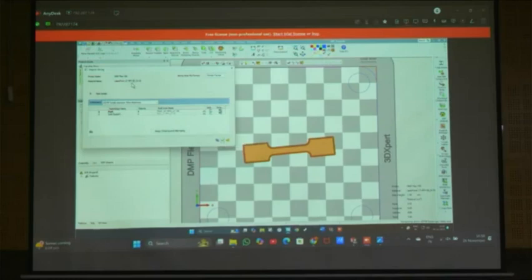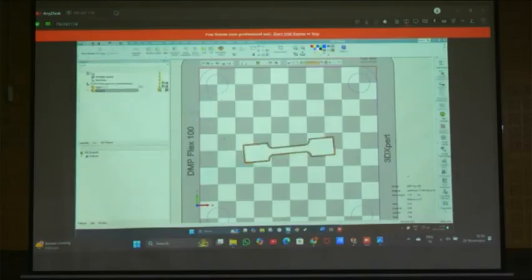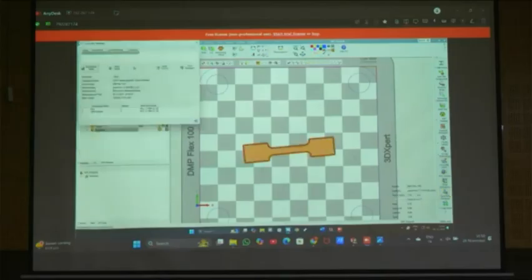You can change the material also, titanium, aluminum, cobalt chromium, whatever the machine can support. So it will scan the path, and once we have completed this calculate slices, then we can change our parameters in the scan path manager. You can see here, scan path manager is there, means we can manage the scan path. So recalculate slices.